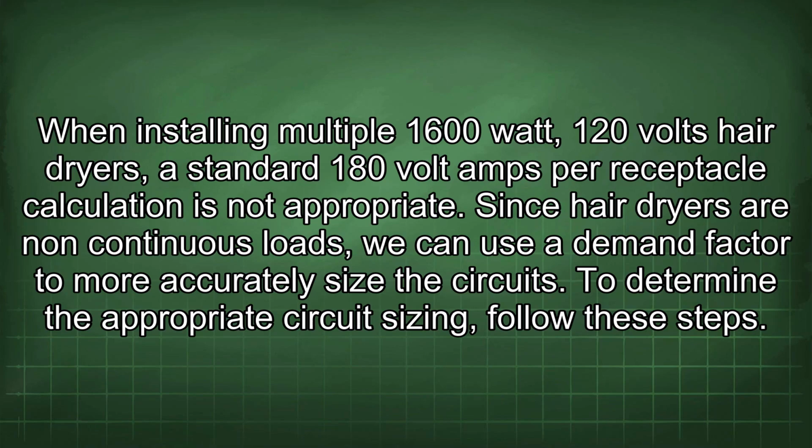When installing multiple 1600 watt, 120 volt hairdryers, a standard 180 volt amps per receptacle calculation is not appropriate. Since hairdryers are non-continuous loads, we can use a demand factor to more accurately size the circuits. To determine the appropriate circuit sizing, follow these steps.